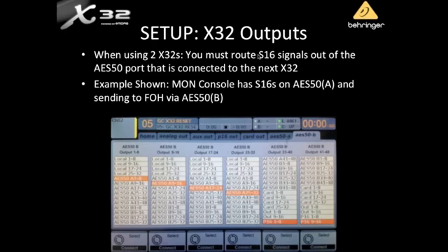One thing I want to mention on the outputs really quickly also is if you're using an S16 and you're doing multi-track recording, you do need to change the card output tab of the routing menu. By default, it's going to be set up for local. That's what gets your local mic preamps down to the XUF card.